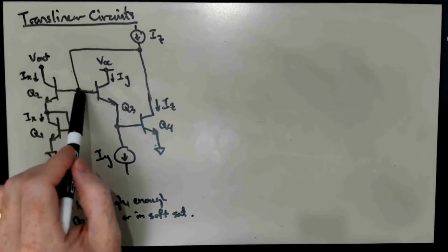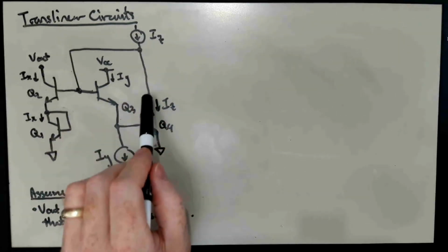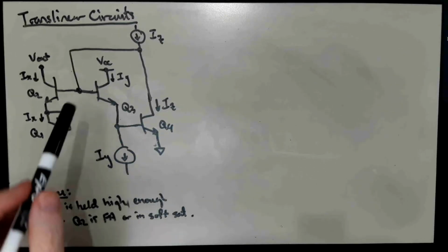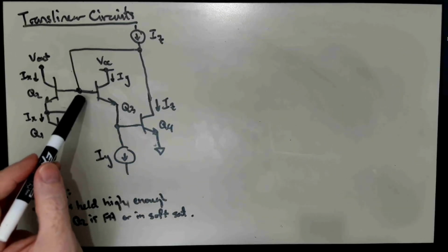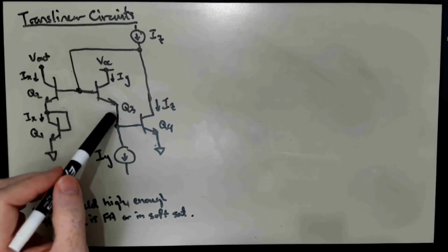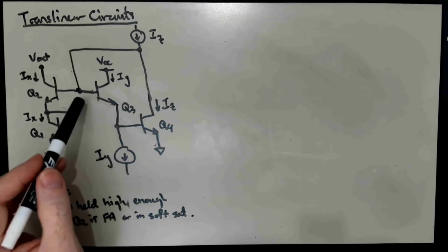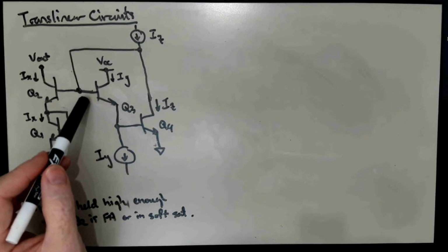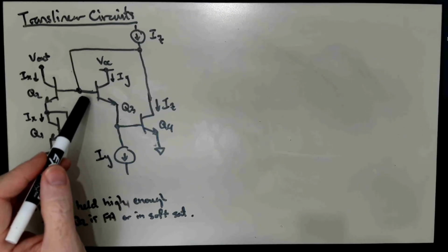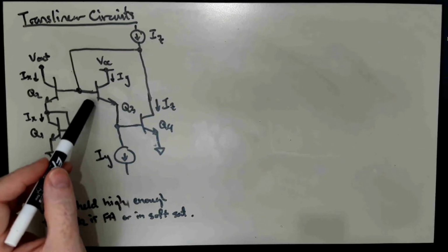So we've taken that point and we've connected it to the collector of Q4. And that's kind of like a diode connection. It's not a direct diode connection, but it is a diode connection through Q3, which we just said was like an emitter follower. And so just like the beta helper transistor when we talked about the current mirror, we could make the diode connection through a buffer, and modulo the level shift, it will do the same thing.